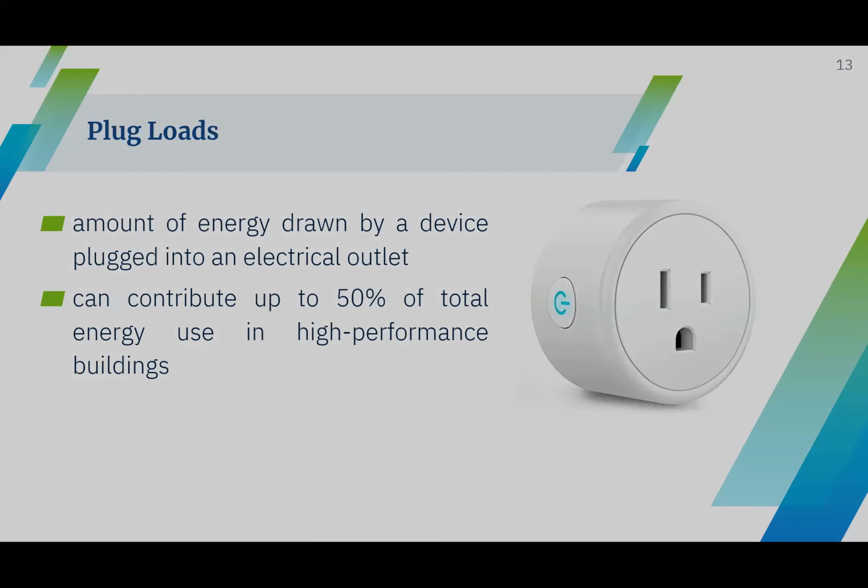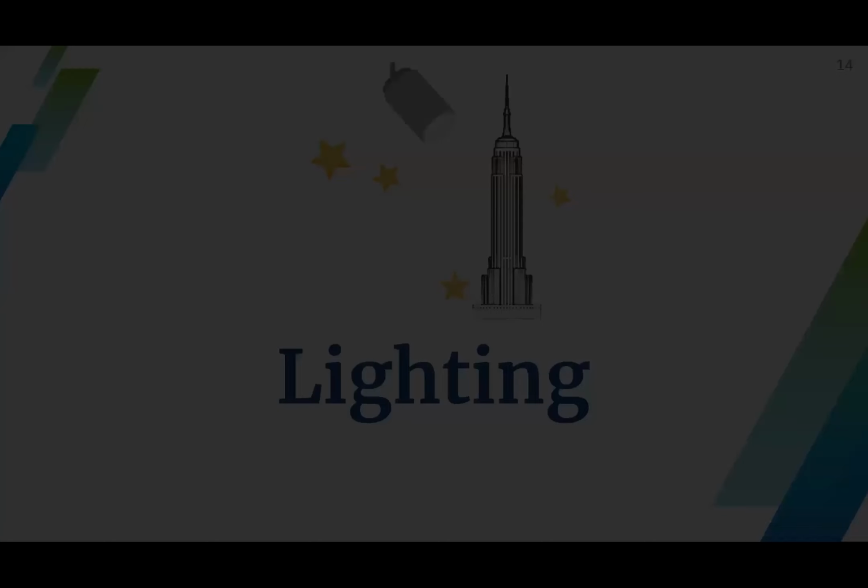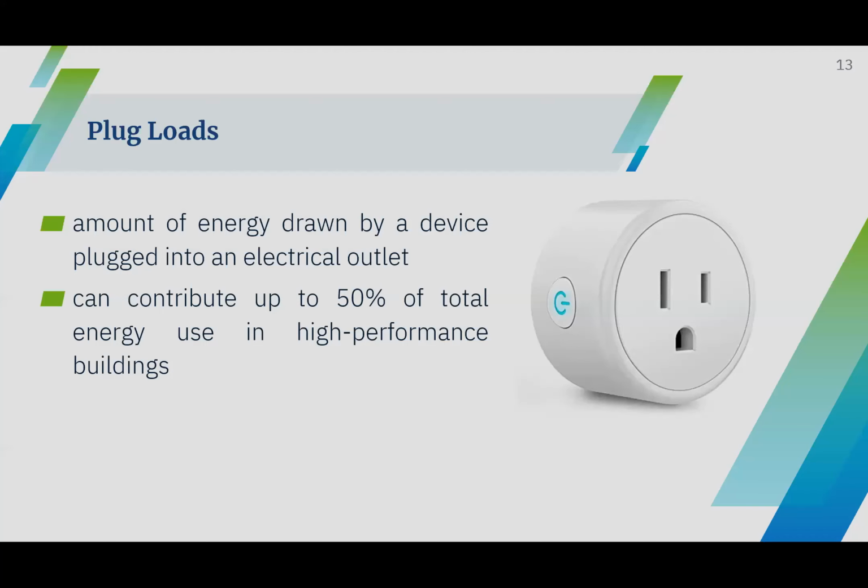We have automatically controlled receptacles that are known as smart plugs. They easily replace existing receptacles and communicate with a controller such as a timer or occupancy switch. The fact that we can monitor and manage plug loads and make them remotely turn off based on feedback from occupancy sensors located in tenant spaces is how we can reduce our energy consumption.